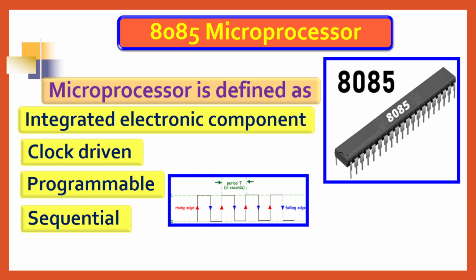Whenever it is powered on, the microprocessor will start fetching the instruction from the first memory location. Then automatically it keeps moving to the second memory location, third memory location. Likewise, whatever number of memory locations we have, whatever number of lines we have written in the program, they will be executed one by one automatically, with no need of any external intervention.